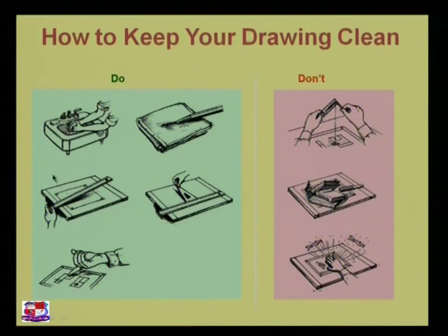Handling of the T-square. If you want to draw a horizontal line, please rest your T-square on the drawing board. Do not hang this T-square. T-squares are very delicate to handle.